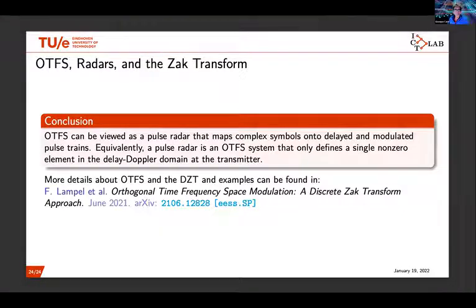Yeah, just a quick question on your last remark. It is true that when you want to estimate the channel and you have this pilot scheme that leaves a blank window with a single pilot, you are limited by, of course, the size of that guard interval. But when you want to use the whole digitally modulated OTFS signal to estimate a radar parameter, the fact that you have zeros or you have known symbols is exactly the same, apart from the complexity. If you can afford the complexity, you can still use the whole frame, and then you have exactly the same resolution in terms of Doppler and range that depends on the size of the whole big frame, not only the pilot.